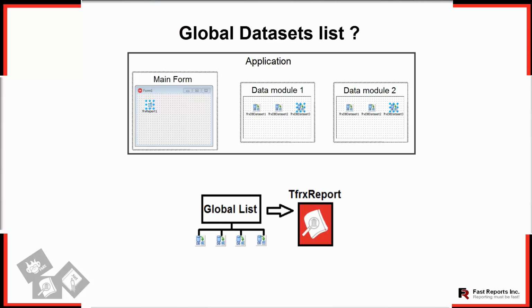It works well with the RAD Studio component model in a single thread, but not with a multi-thread application. For example, we want to create 2 threads. In each thread we create a report from code, and for every FastReport DB dataset component instance we are using the same name for the FastReport DB dataset component. What will happen here?